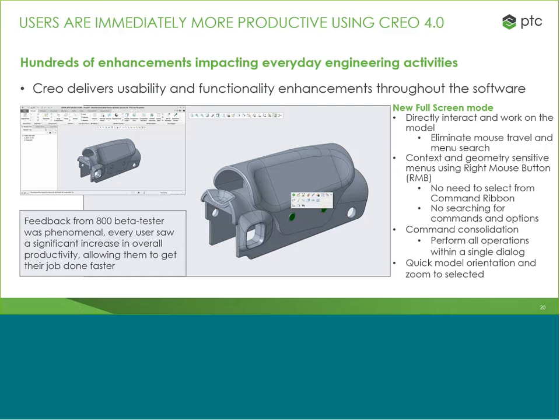In that one consolidated command dialog, I can create my wall, I can edit my sketch, I can add my bend relief, and do any number of things. So what this means to me as a user is I don't need to create multiple features as separate entities. I do it all within one simple dialog. We've done this throughout Creo to take these commands and consolidate where and when it's possible.